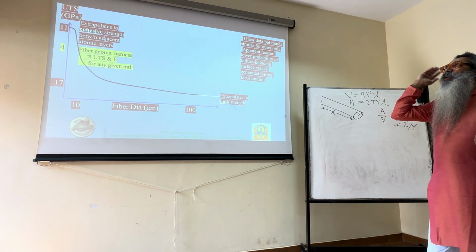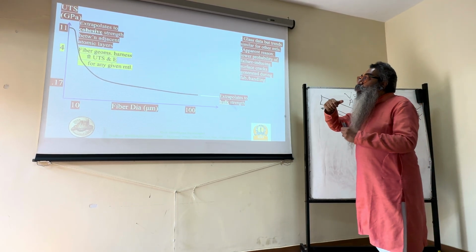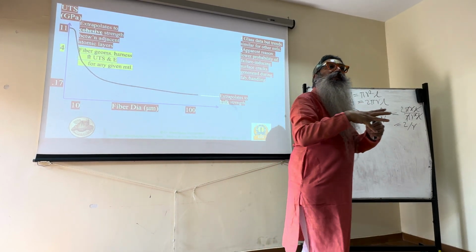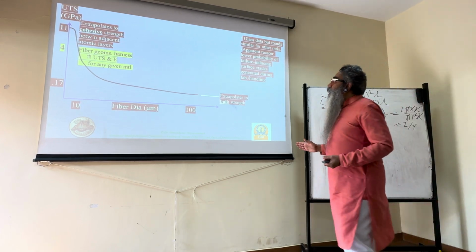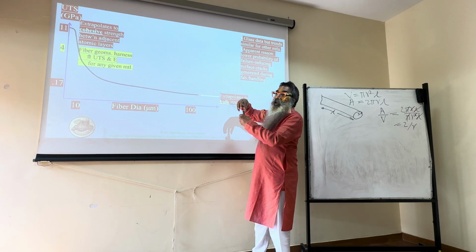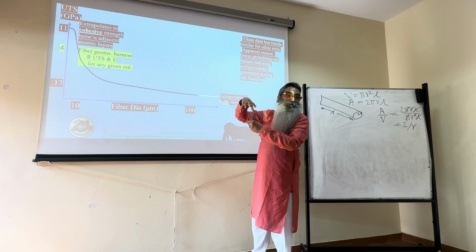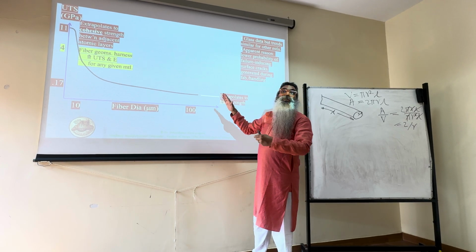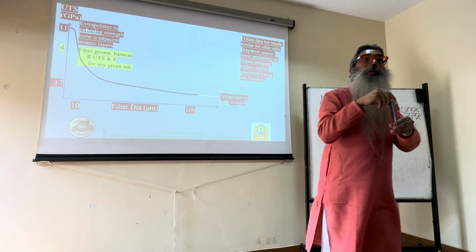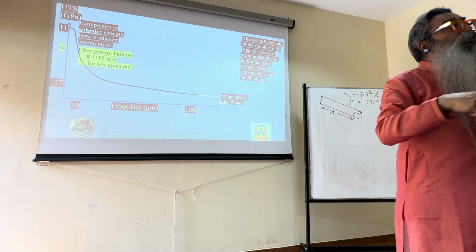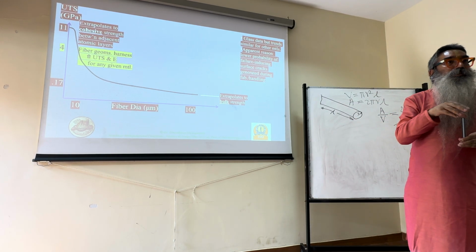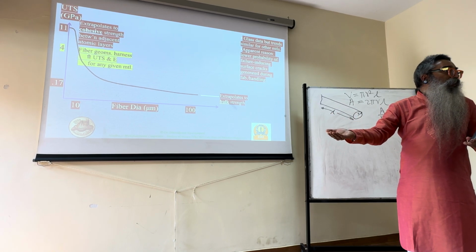But what you were talking about earlier is in terms of the force. Yes, force is the stress multiplied by the cross-sectional area, and therefore if you are increasing the cross-sectional area, you will increase the force. That is valid only in this range where the UTS remains constant. You're just going on multiplying by larger and larger diameter rods, all rods, not fibers. So yes, what you're saying is right, that the stress at which failure occurs remains the same, but the force at which the failure occurs will increase because the area is increasing, right? Because force is equal to stress times the area, right?